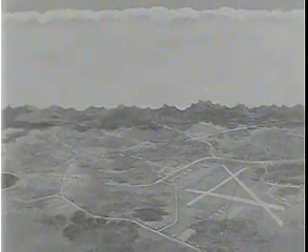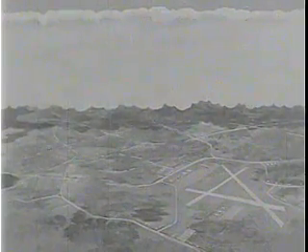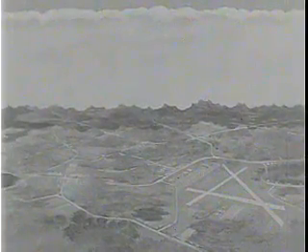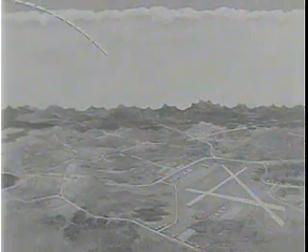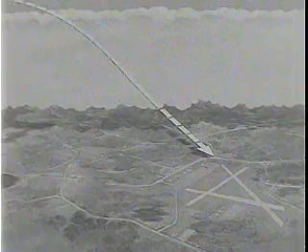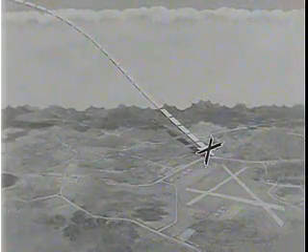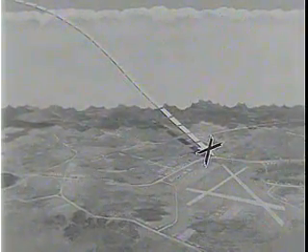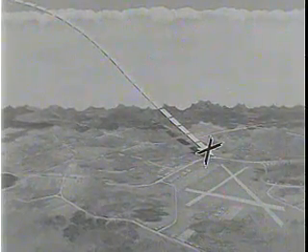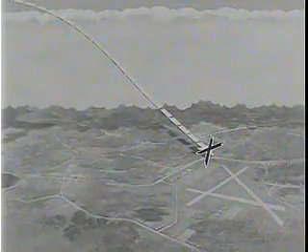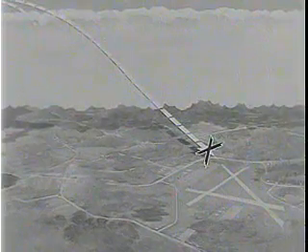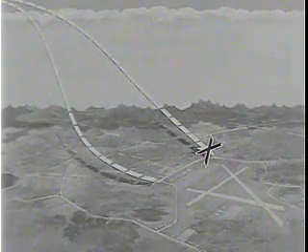When landing at an airport which is overcast and where icing conditions exist, the pilot who uses the normal slow descent will break out underneath the clouds with his aircraft heavily iced. Under these conditions, the landing descent or takeoff climb should be accomplished as rapidly as possible to shorten the time spent in the clouds.